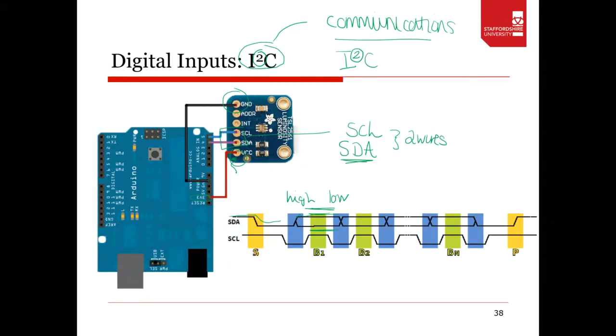Because it's upside down, I read it as 3 but it's 3.3 volts, because the Arduino can either supply a 5 volt supply or a 3.3 volt supply. Good question. In this case, this particular board requires 3.3 volts rather than 5 volts.